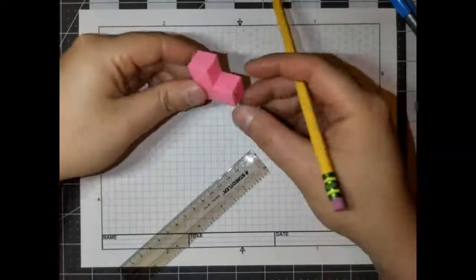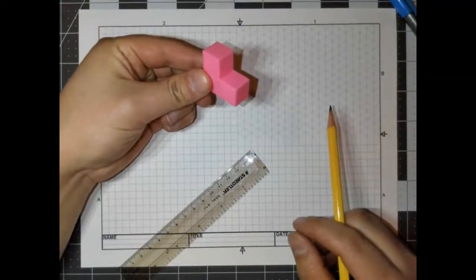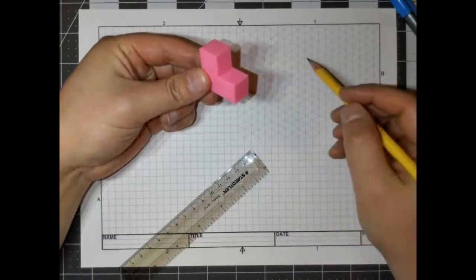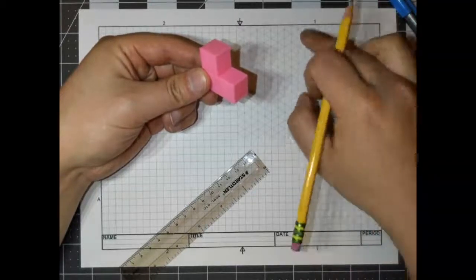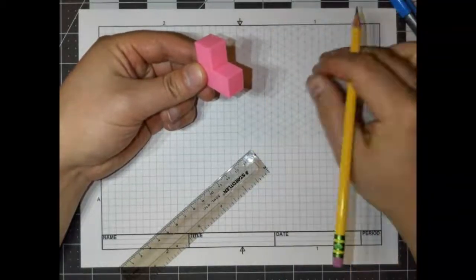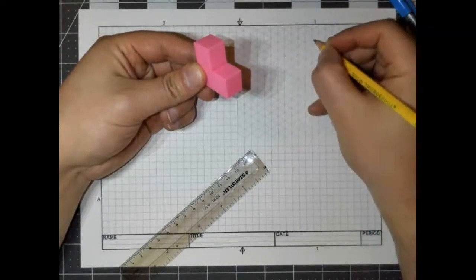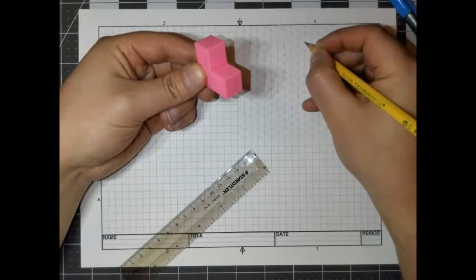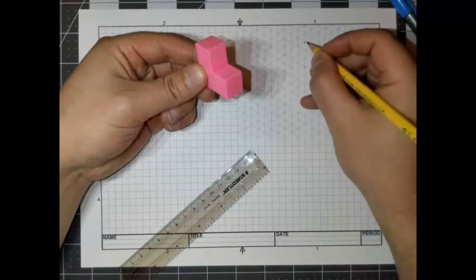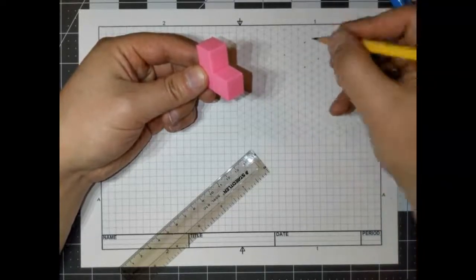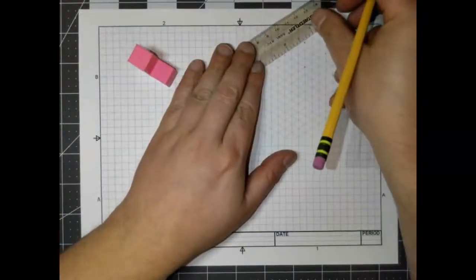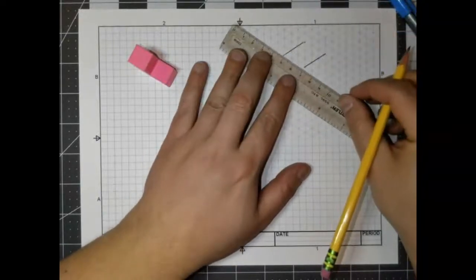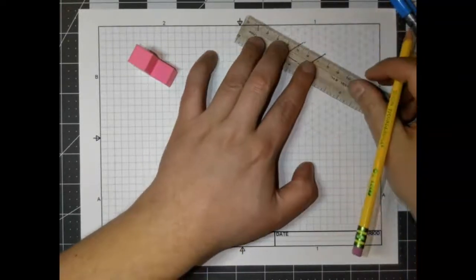Okay, so isometric. Just hold the part in front of you so that it looks like that, to get an idea of how you're going to start. And then on your isometric paper part of your multi-view, find a spot near the top and let's make a couple dots. So 1, 2, 3, 1, 2, 3, 1, 2, 3, and you're gonna use your ruler to draw the top of that object.